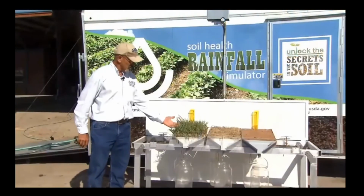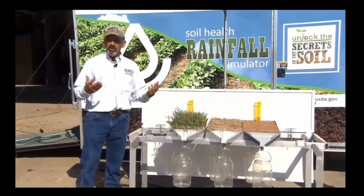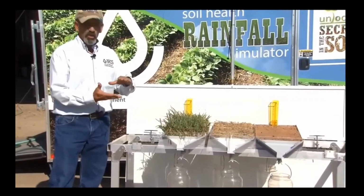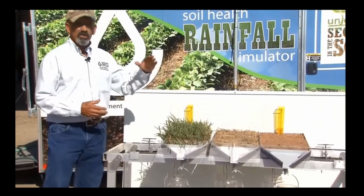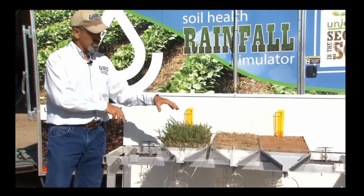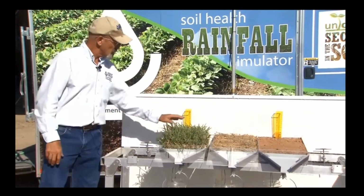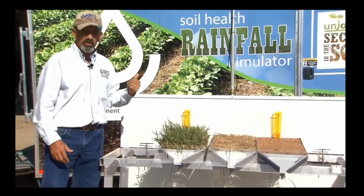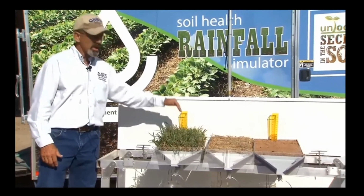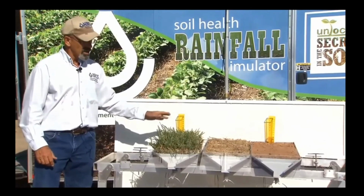And additionally, if you look at these pans, they're about 2 inches thick, and the ideal soil would have about 50% pore space. So with a 50% pore space in a 2-inch pan, you would think 1 inch simulated rainfall would totally saturate that soil, and you would start to see flow through if every drop of water went into the soil. So what we're going to do is, in a minute, we're going to turn the rainfall simulator on, and we're going to watch, and when we get about 1 inch of simulated rainfall on there, we're going to cut it off and look at the results.